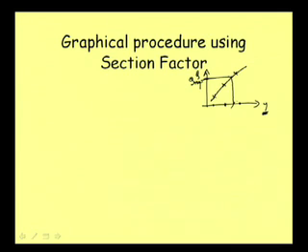It is basically nothing but trial and error: we use different y, calculate Q, and plot a graph. From that graph we get our y n for the given Q, other things being the same, that is, the other sectional parameters like b and z remain the same.